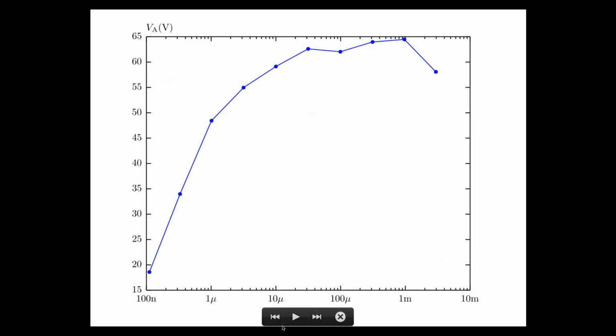All right, well, this is saturation current on the horizontal axis here, and I have Early voltage on the vertical axis. And our typical notion is that Early voltage is a constant as a function of current. And you can see up here, in, say, strong inversion, it's not changing by too much as we change the current by a factor of 200 or something like that. It's changing from some 58 to 60 or something like that.